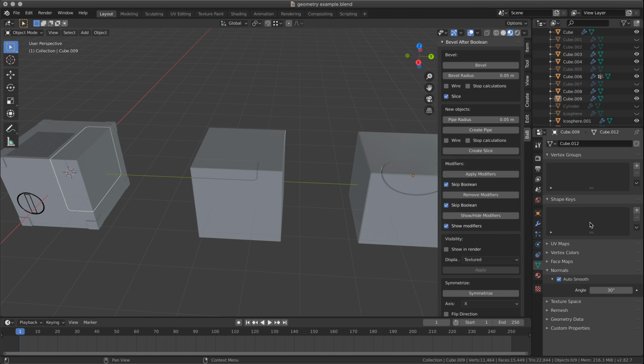One other way is actually building the bevel in the original cutter. So when you are going to cut, you already have the bevel at the size you need, if you have an idea of what you're doing from the beginning. Another easy way is, instead of working with solid geometry, you can work with faces, one or two faces at a time, and then assemble the whole thing at the end.